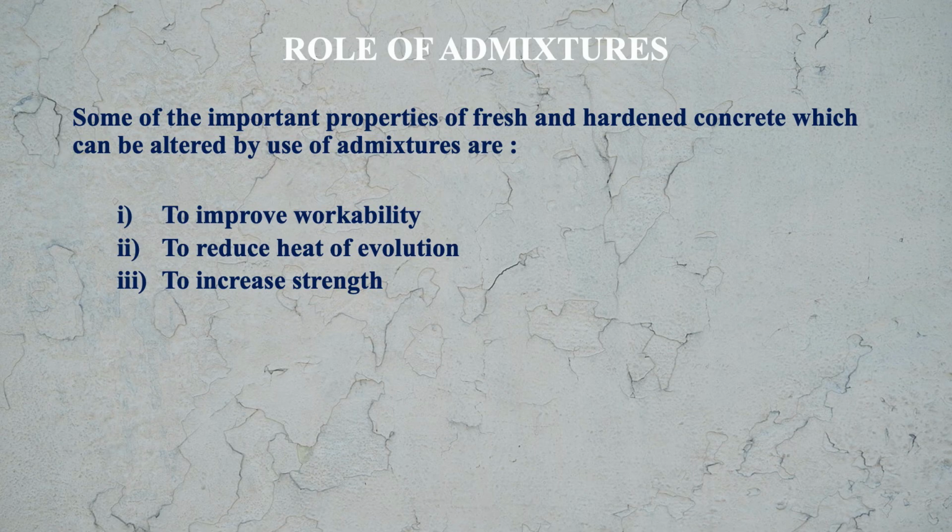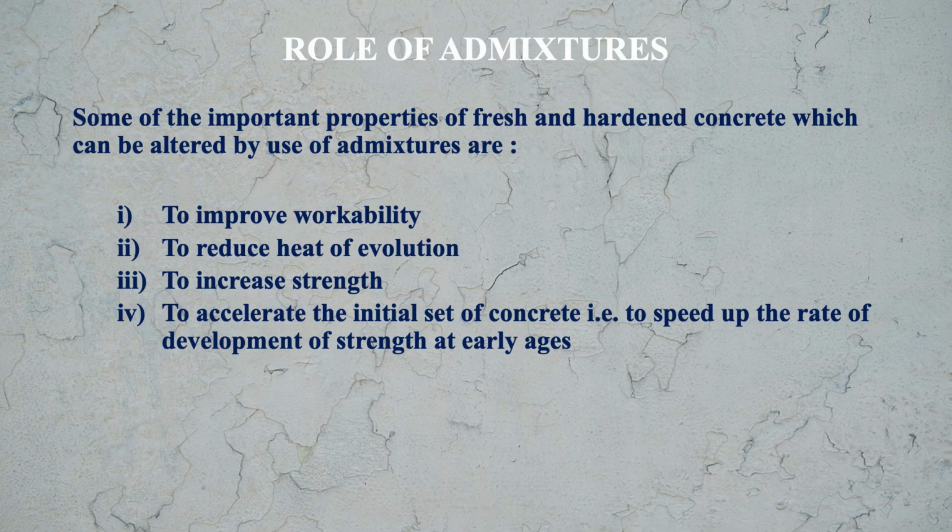We use admixtures to increase the strength of the concrete. Next is setting time. We use admixtures to accelerate the initial setting of concrete, that is to speed up the rate of development of strength at early ages.